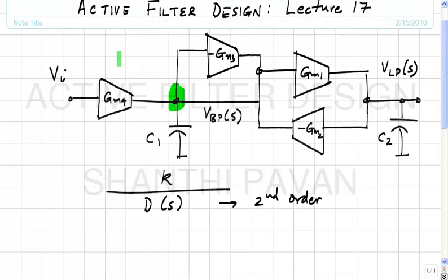And one thing that's also understood is that these transconductors have additional terminals which are the supplies. Okay. You just can't have a voltage controlled current source floating in thin air, right. So there are supplies, which basically means that you can assume that the filter is operating between some pre-assigned supply voltage, okay, one being ground and the other being some supply voltage, like all active circuits.